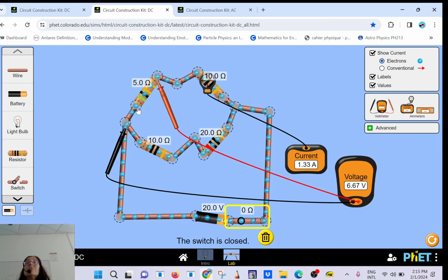If you use your textbook, the real equation is V RMS equals 1 over square root of 2 times the peak. And 1 over square root of 2 is about 0.7. So you can even say that the peak value equals square root of 2 times the RMS, or the RMS divided by 0.7. That's the real equation. Is that clear? Any question?